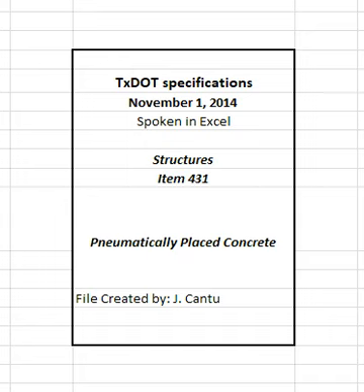Provide materials in accordance with the pertinent requirements of the following items with the exceptions noted in Section 431.2.1, exceptions to Item 421, hydraulic cement concrete, Section 431.2.2, exceptions to Item 440, reinforcement for concrete, and Section 431.2.3, exception to DMS 6310, joint sealants and fillers.